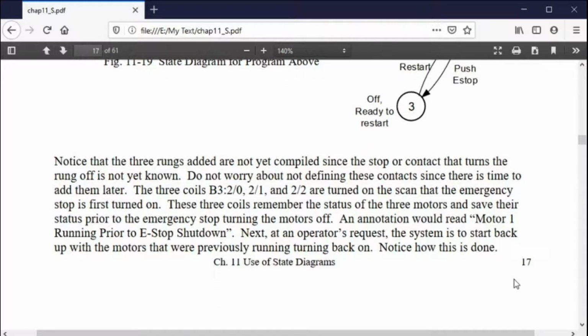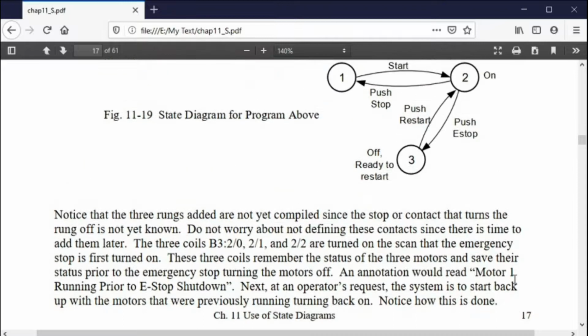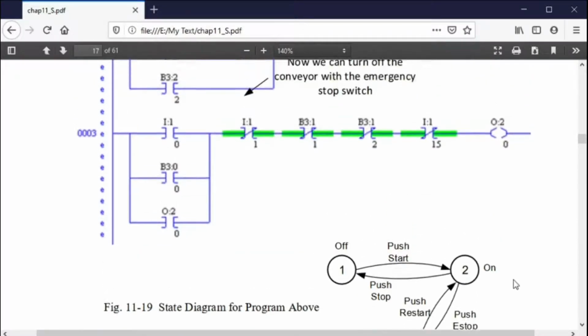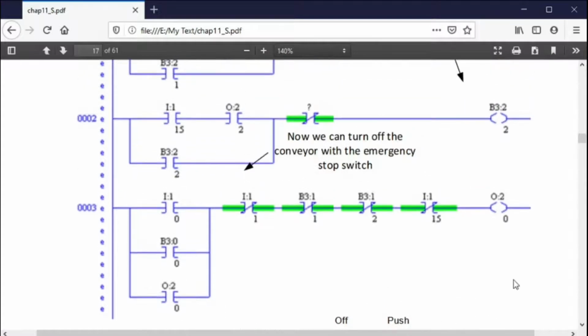You say, what did he just say? Believe me, if you get into problems like this, please come back and review this kind of thing, because it helps to say, okay, he got me at scan. Well, the scan of the program is important, that you set logic in an order. Here you're setting the logic, and then you're using that for future statements, and then you're coming back and you're remembering certain things, and you're using it as you flow through the logic again and again and again.